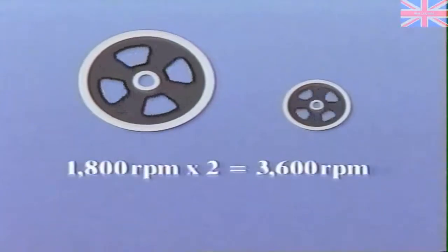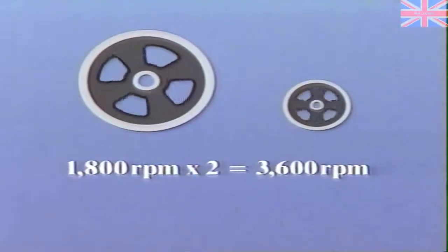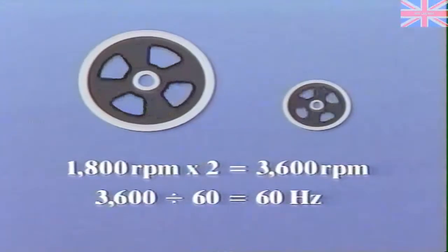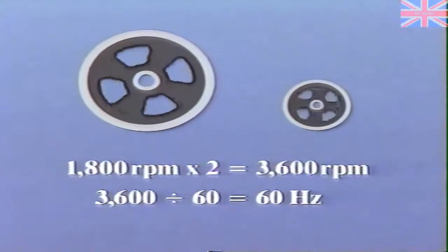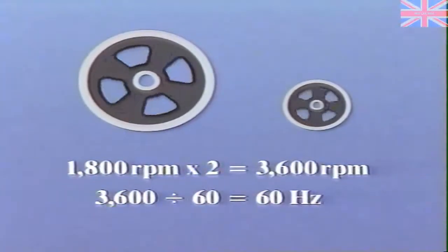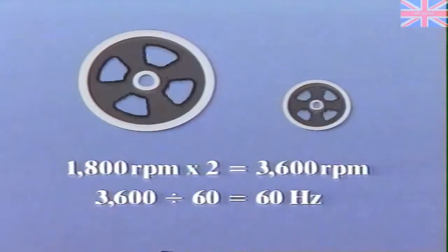The crankshaft pulley will rotate at engine speed. For example, if the crankshaft pulley diameter equals 4 inches and an accessory pulley has a diameter of 2 inches, one crankshaft rotation equals 2 accessory rotations. At 1800 RPM, the accessory will be rotating at 3600 RPM. The frequency in cycles per second is 60 Hertz. Now, if the problem vibration's frequency is also 60 Hertz, the source of the problem is most likely the accessory.